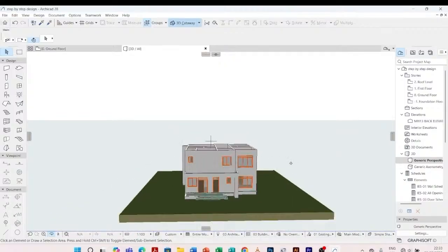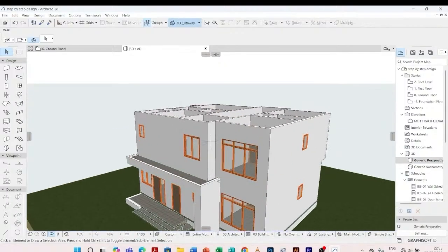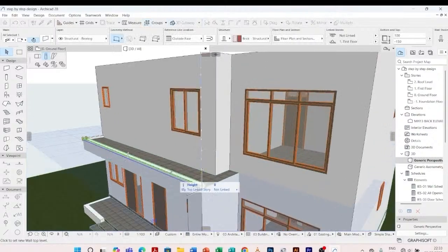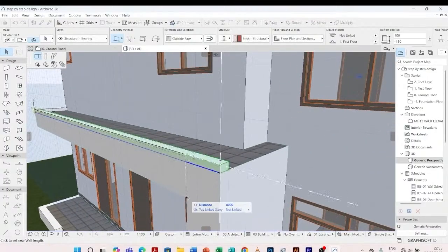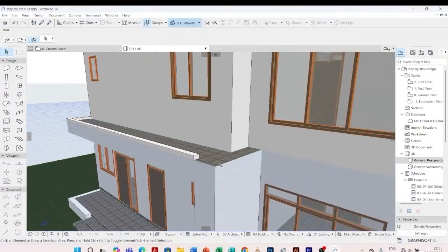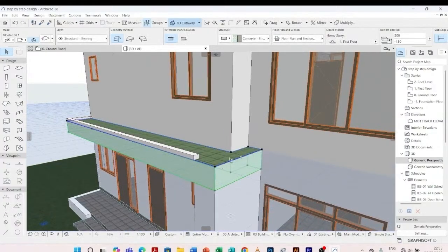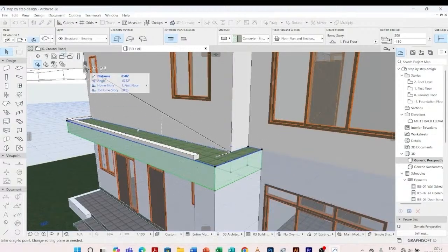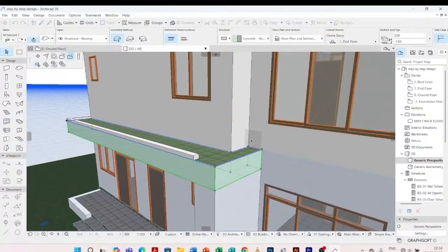So I'm going to do the same for this one so that it also collects water from the roof. I delete this parapet. I stretch the length of this one. It is the first option. I hold on Shift up to this point, and I'm going to do the same for the slab. So for the slab, I can click on any node, then I can cut. So I'm going to cut out this part. This is the subtraction from the polygon, so I'm going to subtract this.